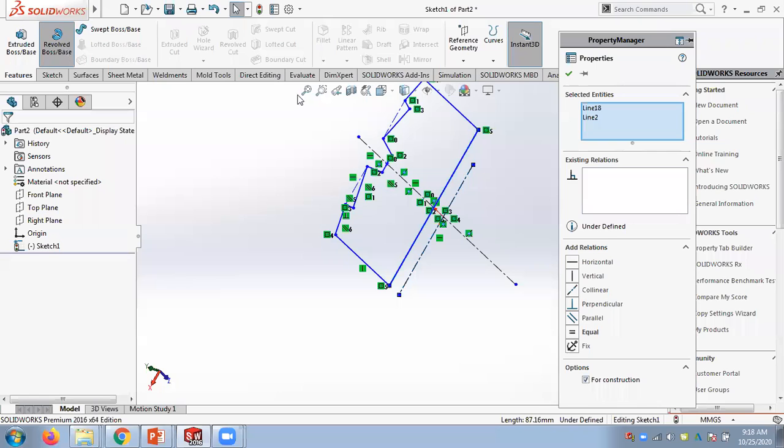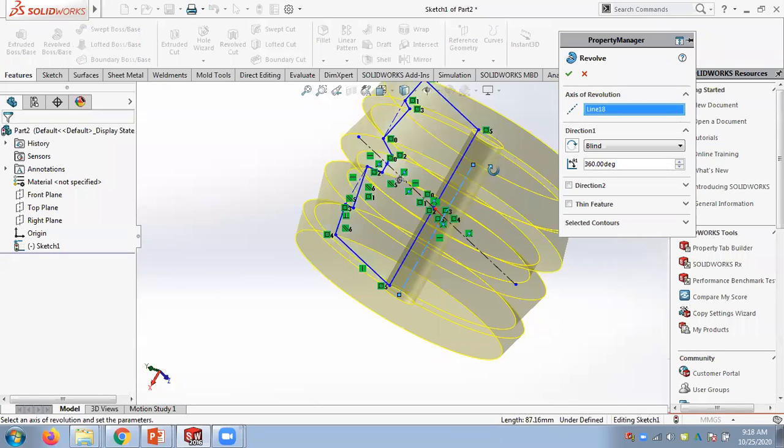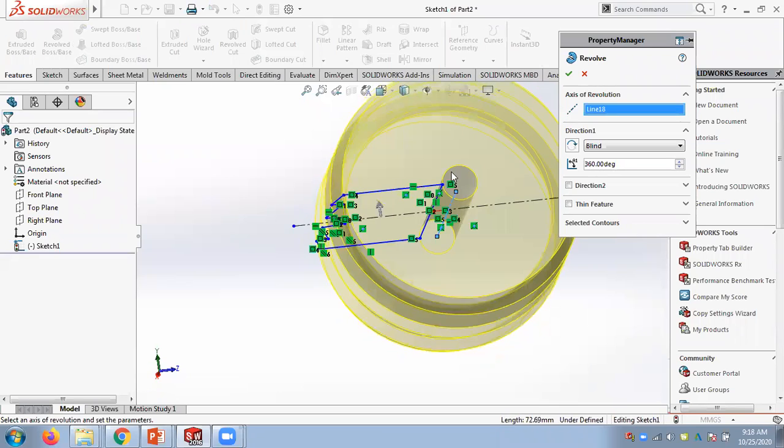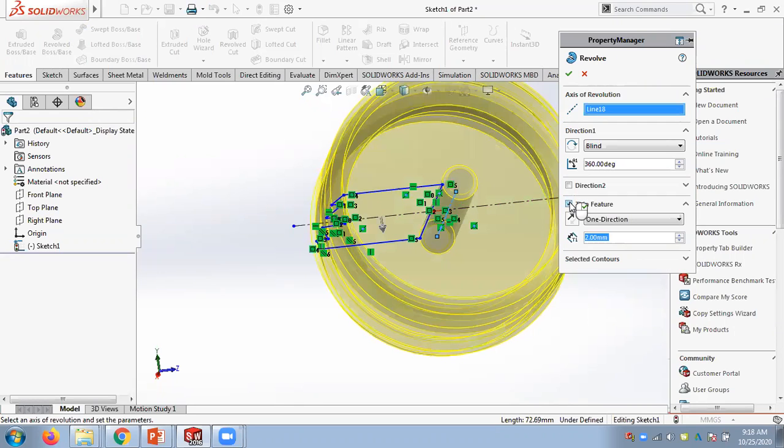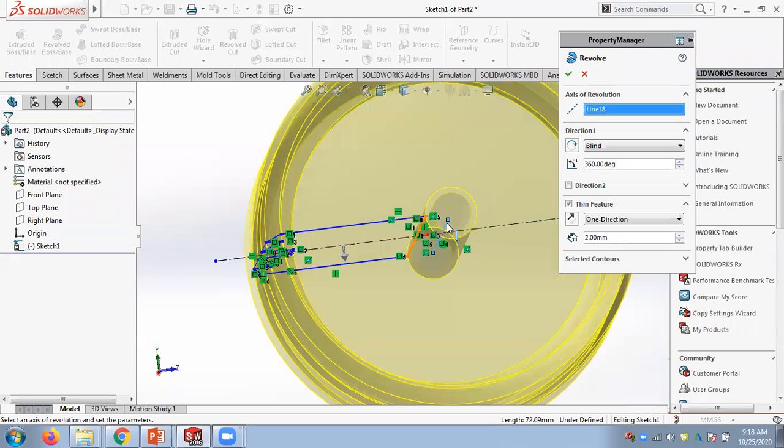So you think a little bit about why it's not working. Now I can get a hollow shape. If I come and hit it with this one, I cannot generate a thickness here. Now thin revolve will work. But when I come and hit this line with this line, where should I get the thickness? I cannot get a thickness. That's why it's not working for thin features.